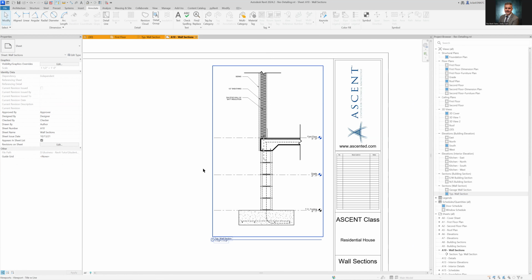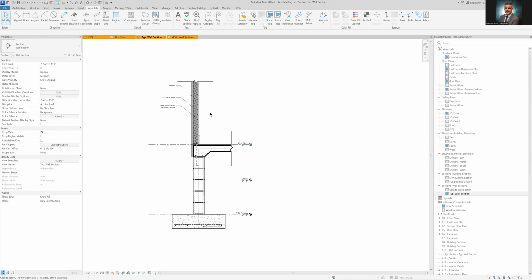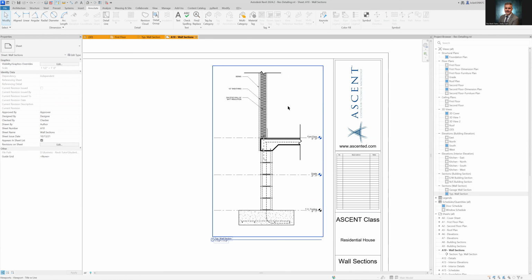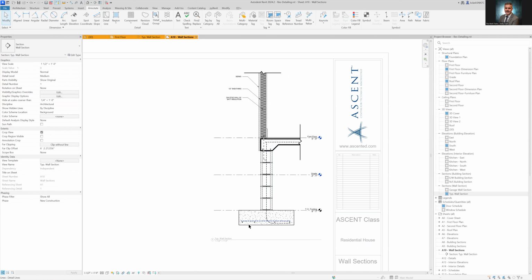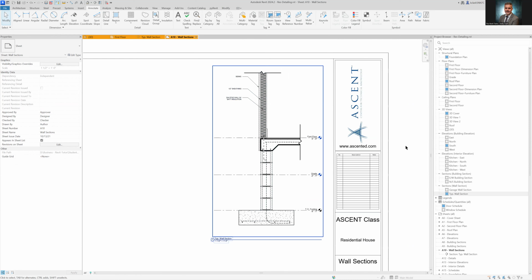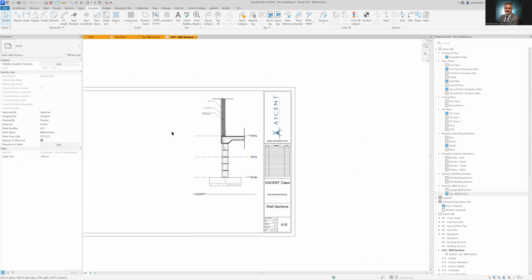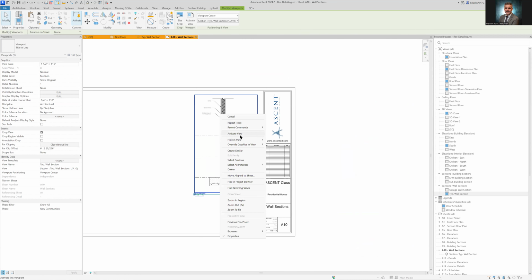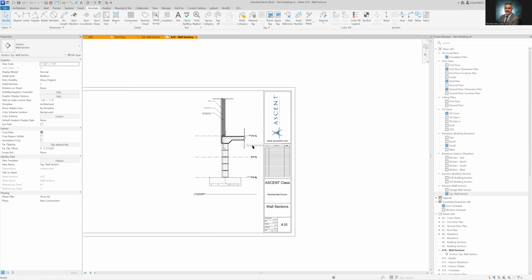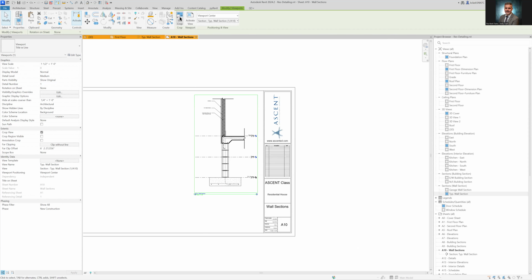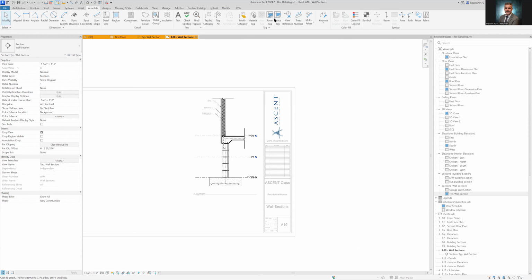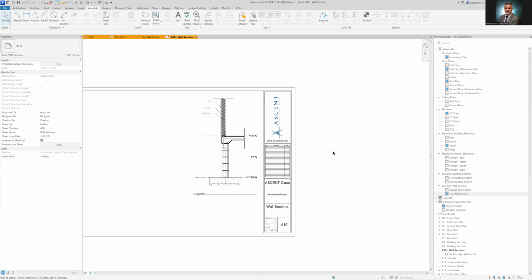And if I wanted to add to it, I could do more things by either going over here to it, changing things if I wanted to. I could double click here to activate this view, and I could work here on the sheet if I wanted to on this one view. Double click off to the side, which is basically away from the border edge of this thing, is where I'm double clicking to get out. There's also right clicks when you select stuff for activating a view, or right clicking again to deactivate a view. Also, it's up here again to activate a view, or again, you don't get to deactivate though, which is kind of nuts. You still got to do a deactivate view that way.